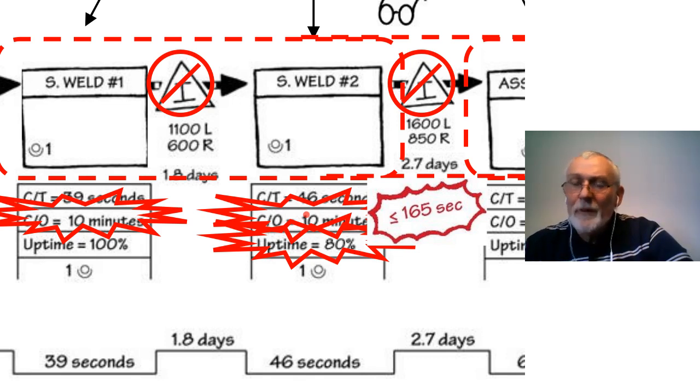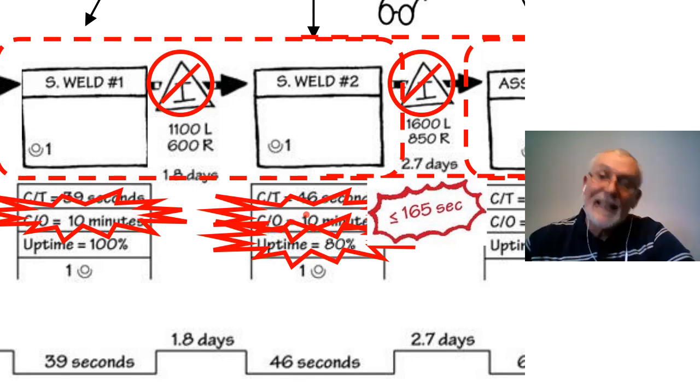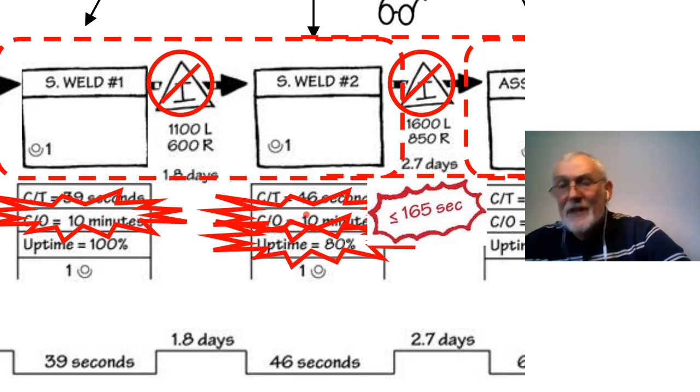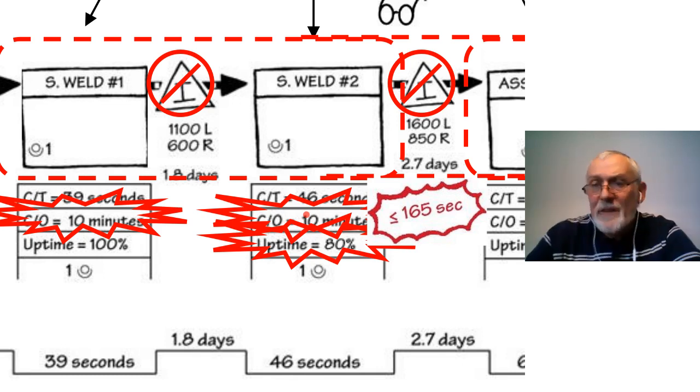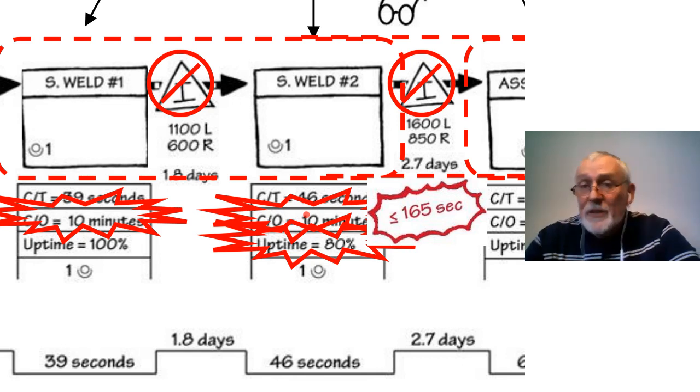Specifically, if you think about the extra work that's often involved in handling batches of work, so putting them into baskets, taking them out of baskets, the handling systems, the stress, the work, when you get into single piece flow, you can often save time just by virtue of the fact that you've eliminated the handling requirements around the batch. Also, fixturing can be redesigned or simplified to take seconds out of it. So it's a job of work that needs to be done, certainly, but not impossible by any means.